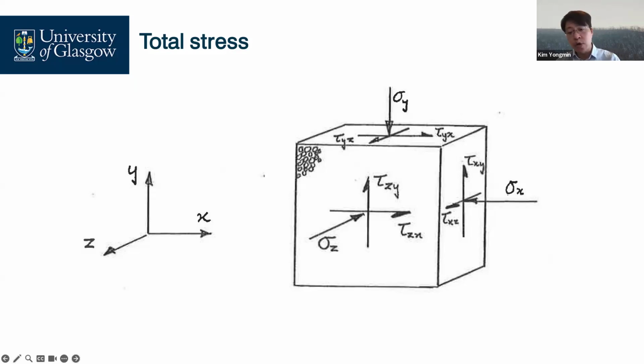Unlike solid mechanics, in soil mechanics we use a sign convention in which compressive normal stresses are positive. Compressive stress is positive because the normal stresses are mostly compressive in geotechnical engineering.